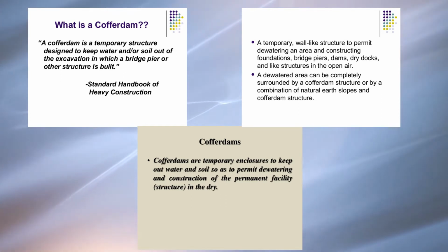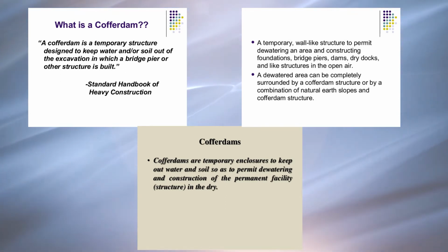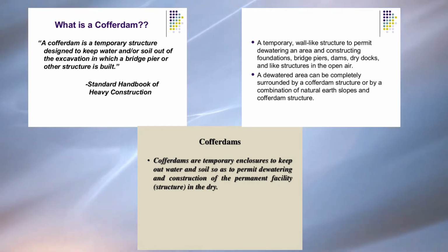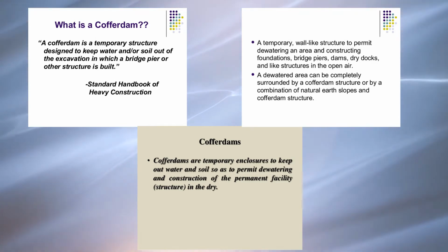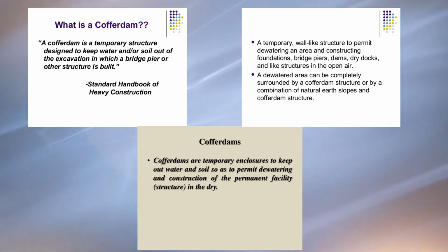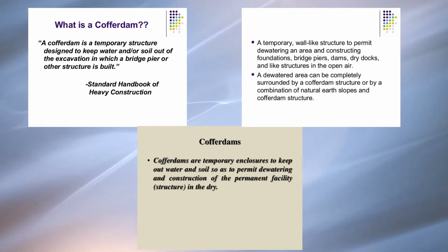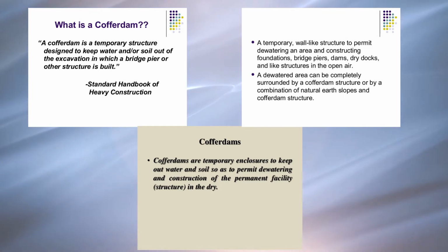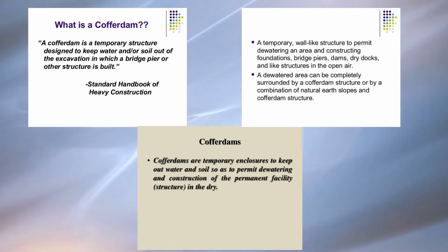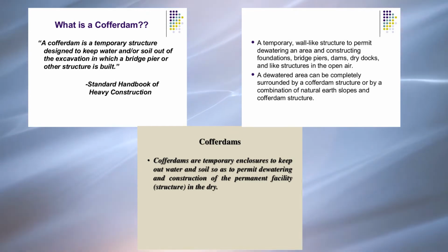Timber sheet piles, concrete, or a combination of materials can also be used. A cofferdam can be any shape. Its design will depend on the depth required, the required working area, soil conditions, fluctuations in the water level, and so on.